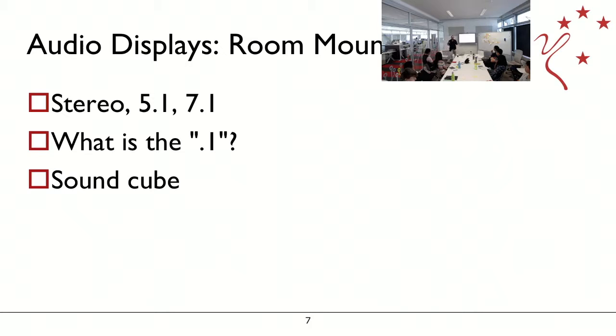And all of the processing was done so that you could actually make a sound appear anywhere around you, because you would just mix the signals going out to these speakers, such that if I was sitting here and you wanted the sound to come from here, then you'd make it so that these speakers contributed a lot more to the sound. Okay? So I didn't have to wear anything, but I had to stay inside this cube in a known location. So I wasn't very mobile in what I was doing. But they worked pretty well.